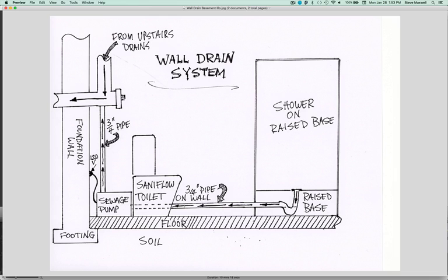You're going to want to arrange things in your basement so that this 3/4 inch pipe, if it has to drain anything else other than the toilet, you're going to want to locate that pipe along the wall somewhere so it's out of sight. Maybe even behind something. Maybe this pipe would travel horizontally through a utility part of your basement, maybe where the furnace is or something like that, and then pop back into the bathroom, your basement bathroom, when it connects to the sewage pump. You're going to need to be a bit creative about how to work this and lay it out so that it works as well as possible.